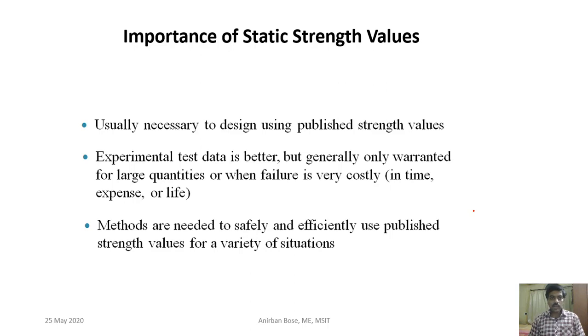So, some of the importance of the static strength values: we have already seen that from the tensile test we get the strength values, right? Like the yield strength of the material or the ultimate strength of the material. This data we get from the tensile test of the material, and these have a very important role in design.